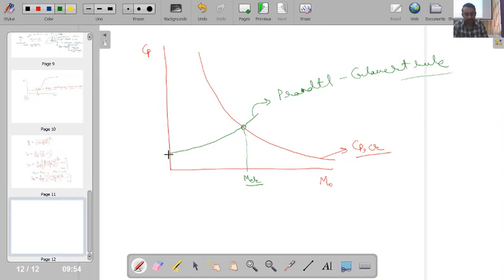If I have an aerofoil, then in case of an aerofoil we have two important parameters. One is the point of maximum thickness, given by T, and then the length from this point to this point is called the chord length, and T by C is the important parameter. Say this is for some smaller value of T by C. If you increase the thickness of the aerofoil, what will happen?